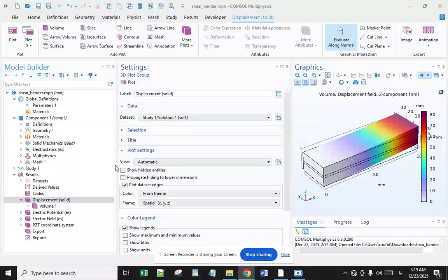The chapter on exact deflection solutions of beams with shear piezoelectric actuators. Exact deflection models of beams with N shear piezoelectric actuators are developed analytically. To formulate the models, the first order and higher order beam theories are used. The exact solutions are obtained with the aid of the state space approach and Jordan canonical form. A case study is presented to evaluate the performance of the other previously reported models.